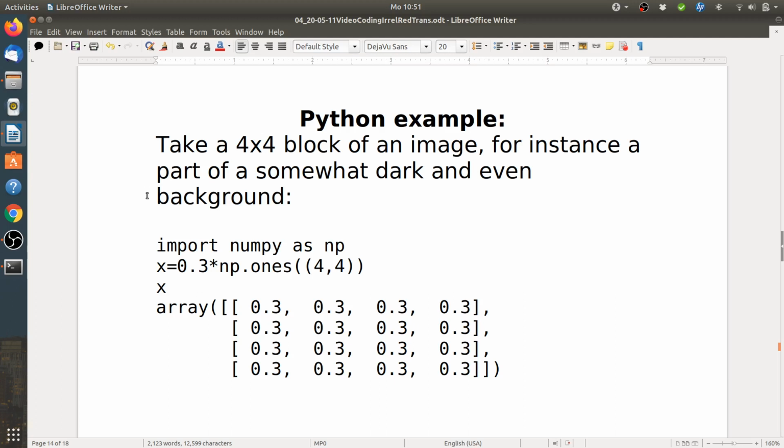Remember, for the DFT we covered positive and negative frequencies, say from minus pi to plus pi. Here we just cover the frequency range from 0 to pi for the DCT, and that means we have a twice as high density of subbands compared to the DFT. So that's also an advantage for image processing.